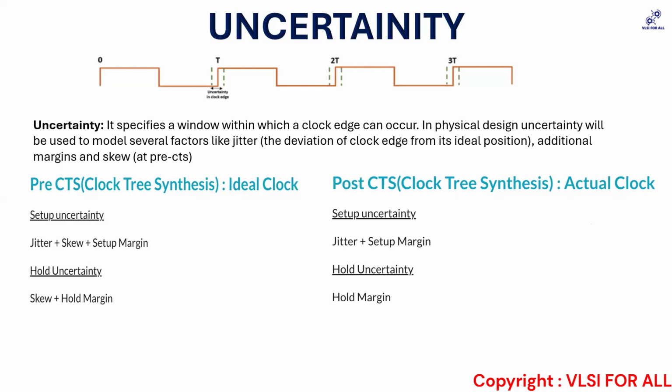Now in post-CTS, since you have designed it, see, guys, when you open up the design in pre-CTS, you will see that there are no clock buffers or clock inverters in your design. There will be no physical connections going through the flops, through the clock buffers and inverters; you will only see logical connections. But once your CTS is there, you have a complete design ready, and you know how many clock buffers and clock inverters it will take. So for the skew I explained, you will have a real picture, and you will be able to calculate it.